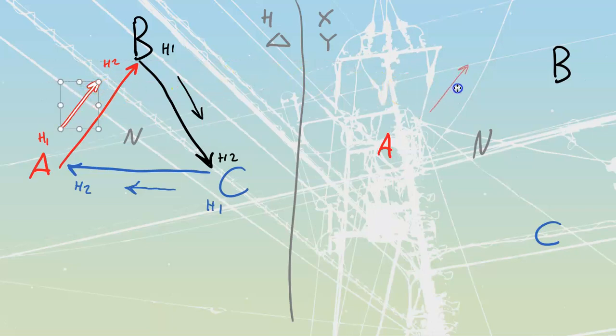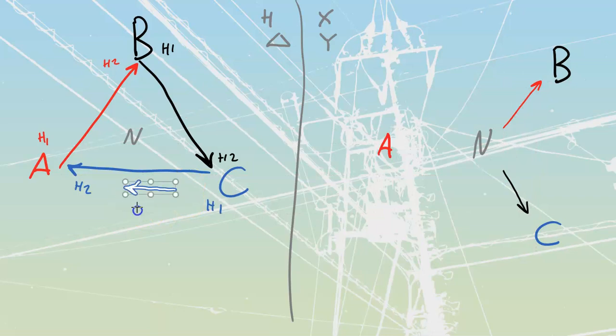So we take this one, we're going to carry this one over, and look for a place where I can fit it. Obviously it doesn't connect from neutral to A, it doesn't connect from neutral to C. The only place where that one could go would be neutral to B, so I'm going to drop it over there. I'm going to grab the next one, do the same thing, and carry it in. A to neutral, it doesn't fill that line. This one's already filled, and it does fill my neutral to C. And we'll grab the last one over here, carry it over, and we see that these two are both filled, plus it wouldn't work in either one, so therefore it's going to have to go across like that.